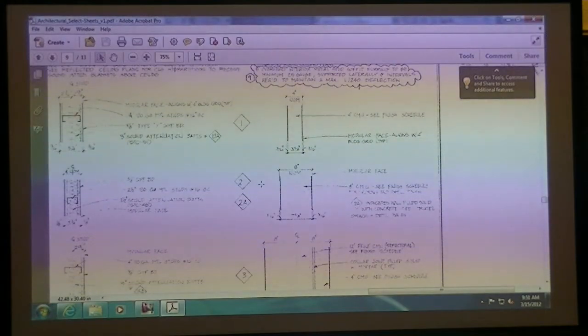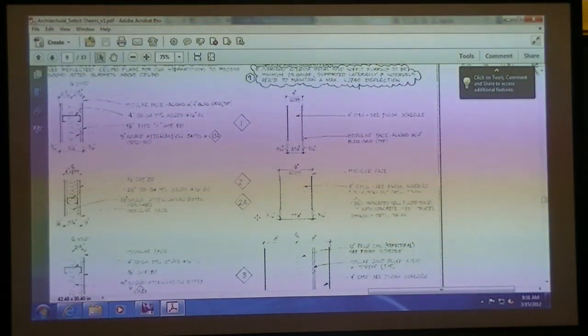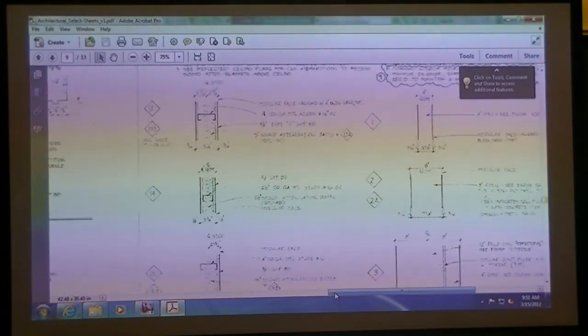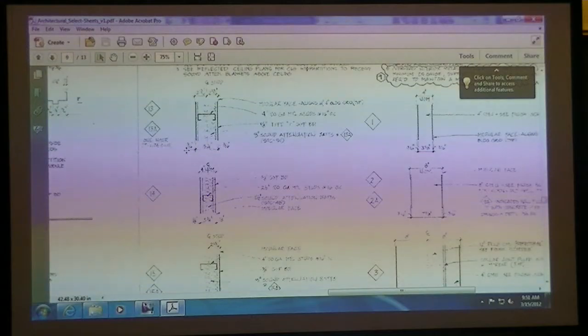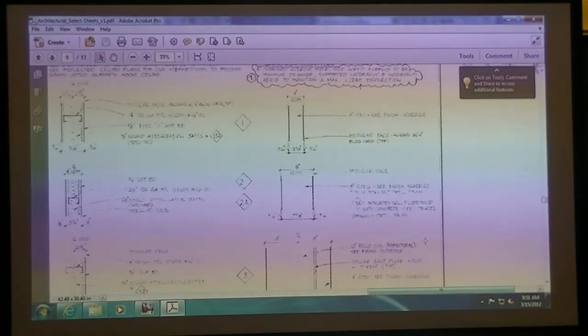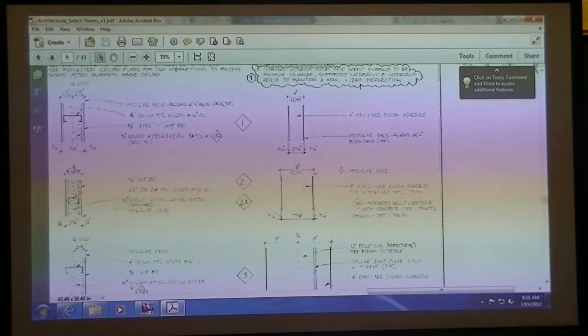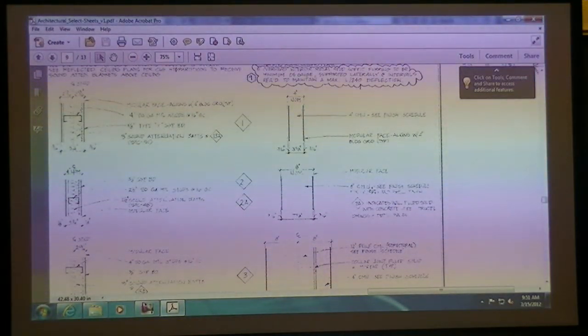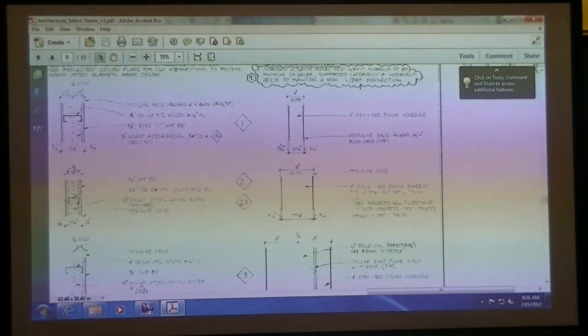Normally a wall type drawing, when it's scheduled, shows a section cut through a wall, and it shows all the different layers of the wall, and usually some sort of overall dimension, and it also calls out what each of the different layers are. One of the wall types we were looking at was a wall type 2, and here it says 8-inch CMU, so it's an 8-inch nominal CMU.